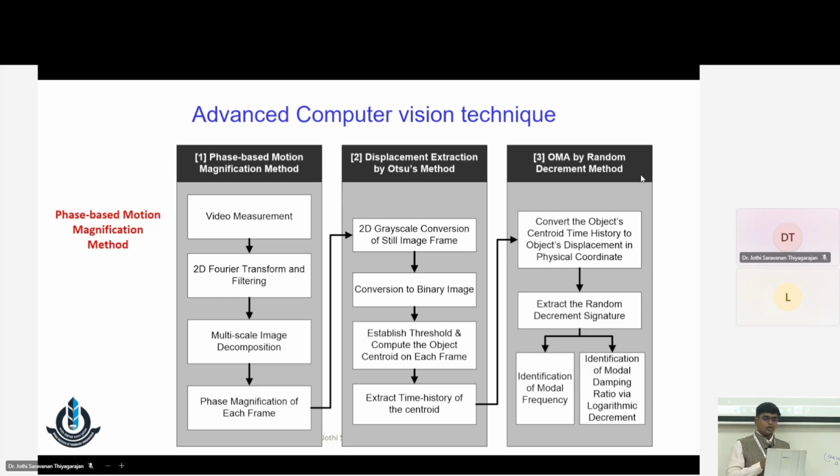When you have a time domain signal and you convert that into the frequency domain, so let us assume the Fourier transform, which is well known to everyone, you get two parameters. One is amplitude and the other is phase of a signal. Once I get these two parts, I'm going to play with the phase of this signal and magnify that part to understand how the system is vibrating. That's the simple layman explanation I can give now.